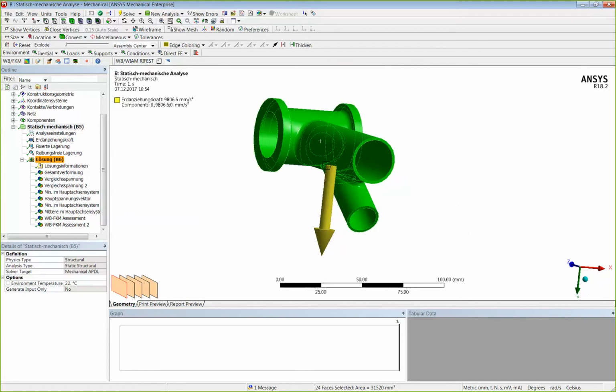Good. The question was also, is there one ACT for shells and for solids? Yes. The structural stress concept is to be expected with solids in the moment, and only with solids. And the nominal stress approach for welds is expected to be with shells. And the unwelded is to be expected with solids.